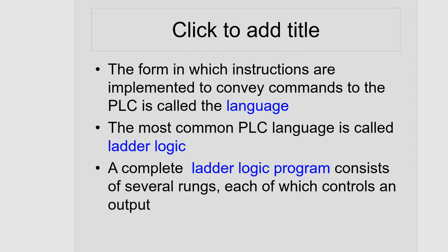We have to understand the language, but it's different with PLCs because the language is designed to look like electrical circuits, and that's on purpose. That's so that a plant electrician can almost look at a PLC program and it looks so much like a circuit that they can understand it. So we program any digital device, including the PLC, with the language, and the language most common to PLCs is called ladder logic. And so we'll use ladder logic programs to get the PLC to do what we want it to do.